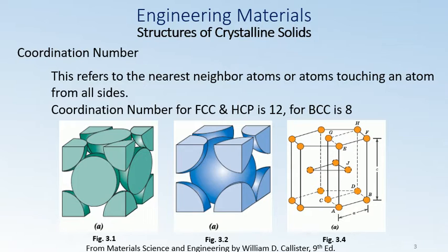And then we have another unit cell that is just connected in front of it, and 4 atoms come in contact from that unit cell. So all these make a total of 12 atoms that are directly in contact with this front face center atom of the FCC crystal structure, and so its coordination number is 12.